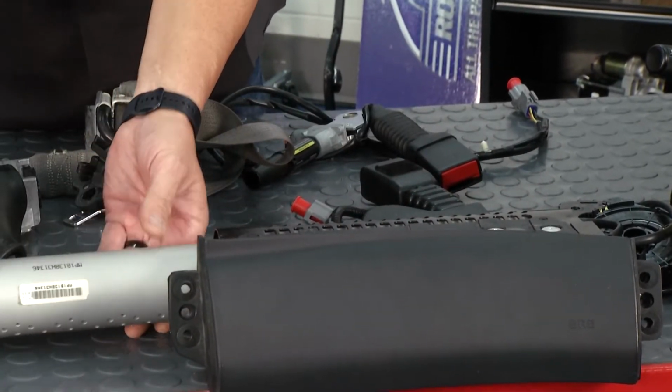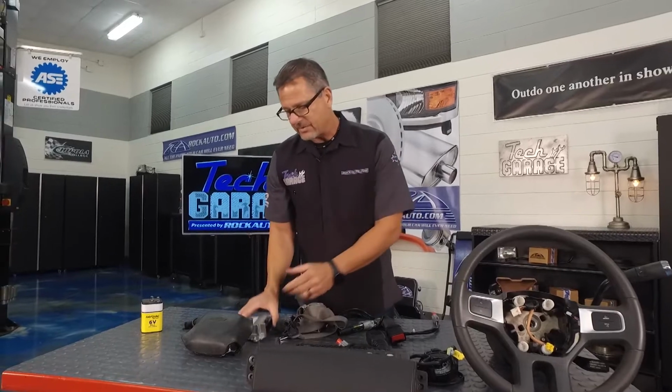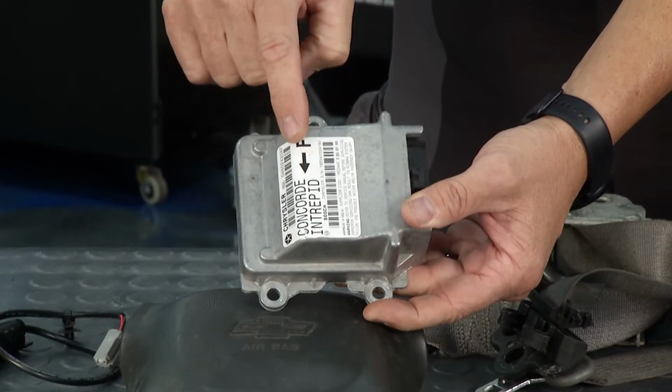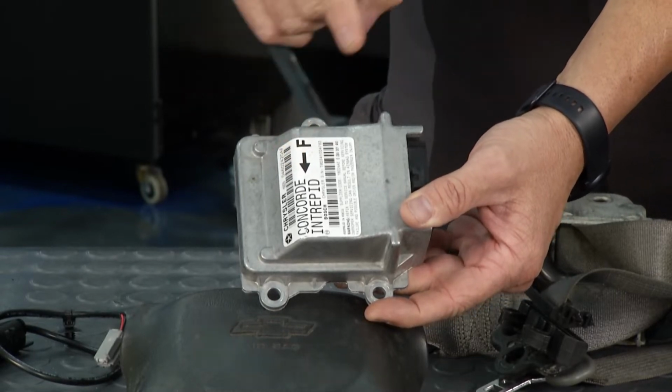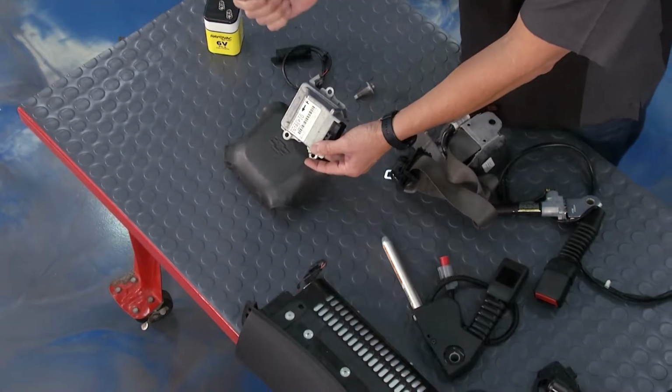These are usually multi-stage airbags today. They deploy with safety weight sensors in the seat, all kinds of electronics going on. You also have a module right here, which is an airbag module. Now, you see the arrow direction? That has to go in that direction. Why? Because it's all about that delta velocity, hitting something. You can't just go up and hit the front of the vehicle, nothing's going to happen.